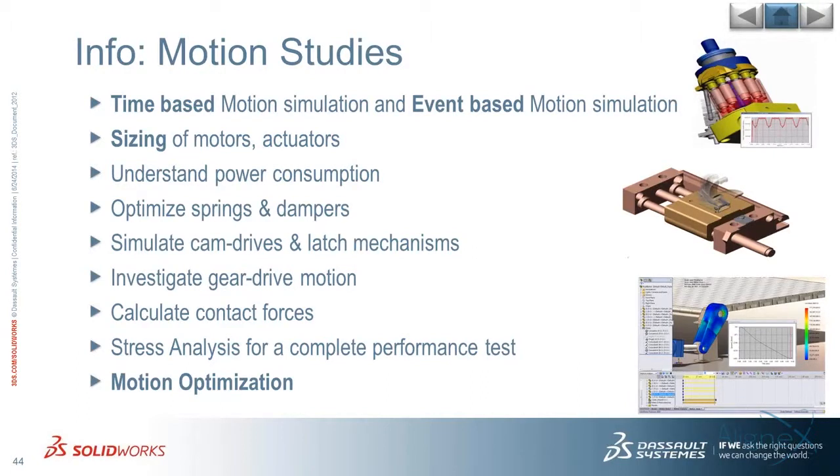So we can do our time-based motion simulation and our event-based motion simulation within Simulation Premium, helping us with sizing of motors and actuators. We can understand power consumption of motors, what sort of power we need, and optimize springs and dampers. We can simulate cam drives and latch mechanisms, investigate gear drive motion, and calculate contact forces between these rigid bodies.